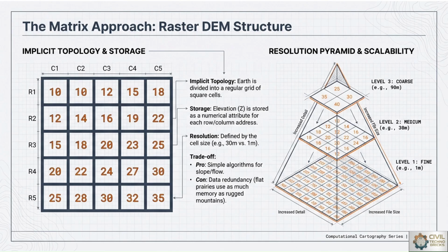So the most common way to represent the elevation is through a raster data structure. In this model, the terrain is divided into a matrix of square cells, and the resolution of these cells, such as 30 meters or 1 meter, determines the level of detailing. While raster digital elevation models are excellent for computational efficiency and area-wide modeling, they can struggle to represent abrupt changes in topography like cliffs or retaining walls which are constructed.